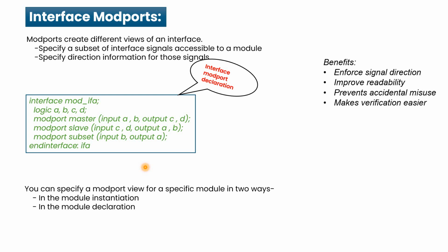And this has been improved by making use of mode port. So mode port is again an enhancement in interface, and mode ports create different views of an interface. It specifies a subset of interface signals accessible to a module, and specifies direction information for those signals.